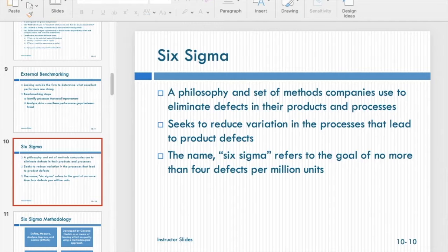All right, if the length of the product that this firm is producing, the target is 10 inches. All right, but we know that even if it's made by a machine itself, we cannot make sure that every unit of product is exactly 10 inches. Right, so instead of setting a target which is exactly 10 inches as a high quality product, in most cases, they will set up a range. Let's say for this product, if it's between 9.95 and 10.05 inches, this is a good quality product.